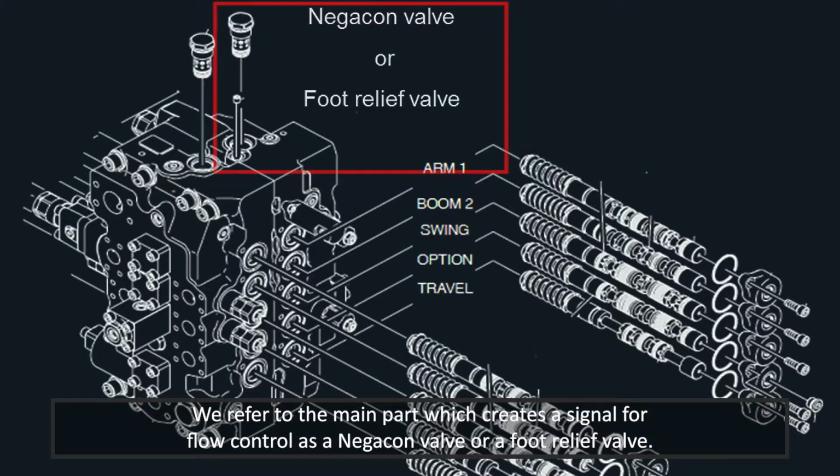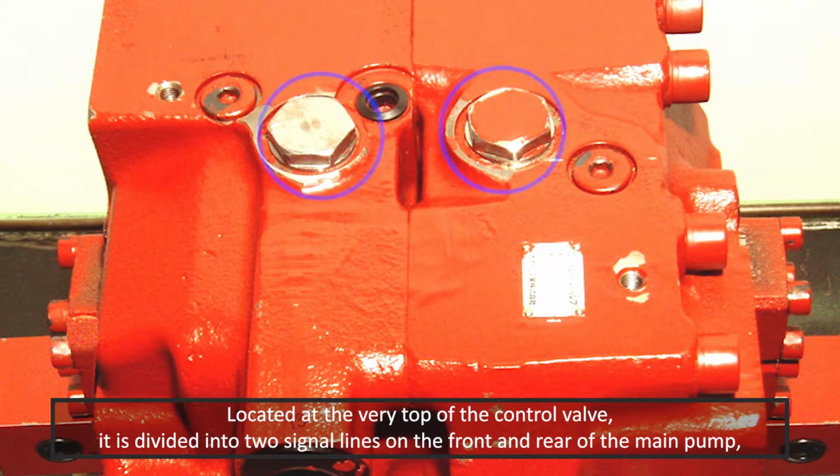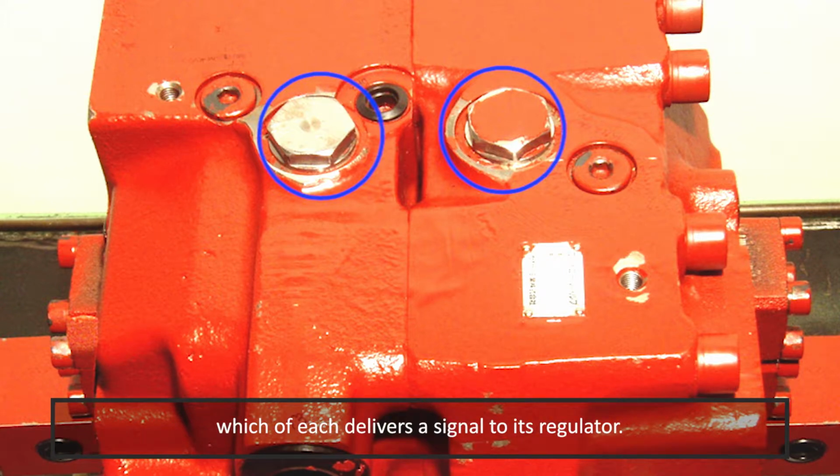We refer to the main part which creates a signal for flow control as a negation valve or a foot relief valve. Located at the very top of the control valve, it is divided into two signal lines on the front and rear of the main pump, each of which delivers a signal to its regulator.